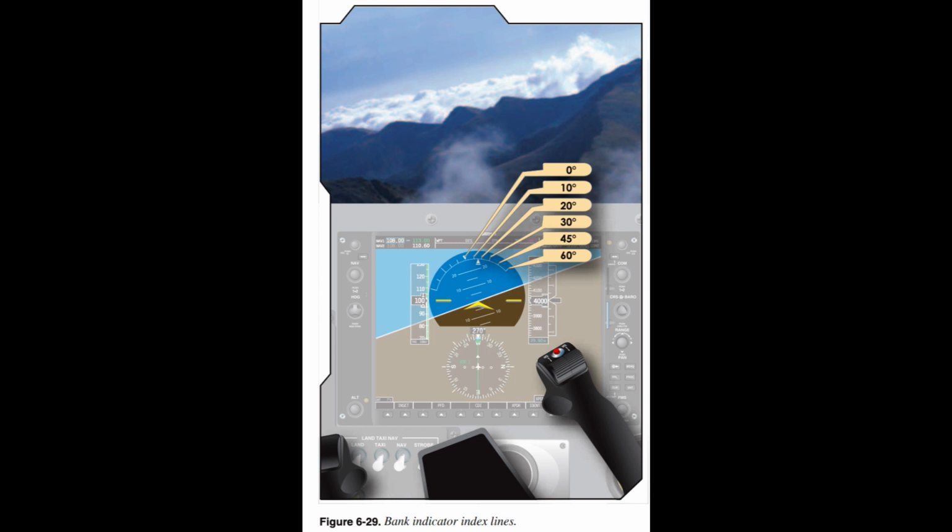Power control. The power instruments indicate how much power is being generated by the engine. They are not affected by turbulence, improper trim, or control pressures. All changes in power should be made with reference to power instruments and cross-checked on performance instruments. Power control needs to be learned from the beginning of flight training. Attitude instrument flying demands increased precision when it comes to power control.